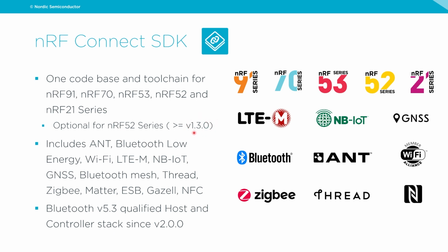But we strongly recommend that if you're doing a new design with the nRF52 series, you do go with nRF Connect SDK. The reason is that the nRF5 SDK is in maintenance mode. It is Bluetooth 5.0 qualified, but we're not introducing any new features into that SDK. So if you are starting a new design, you will want to go with a future-proof solution, and that will be the nRF Connect SDK.